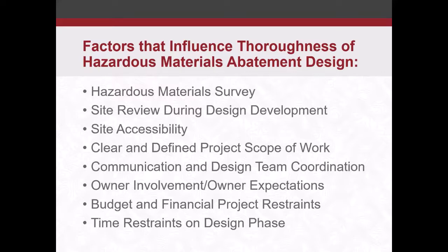If that was done well, and you were able to sample all the materials, you got a pretty good picture of the building, and that design goes pretty seamlessly. If things weren't totally complete and you're having to redo or reassess some things, or it wasn't picked up during that, then your design could suffer. That's why I say it's really important to do a design site review. A lot of people expect that it's in the survey, so whatever's in the survey, do your design on that.